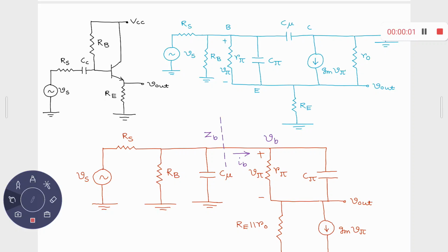Okay, so last day we have been talking about the frequency response characteristics of BJT based amplifiers, and we have discussed one such effect, which is known as the Miller effect, right? In that case, we discussed the frequency response characteristics of a common emitter amplifier, and then the common base amplifier, and then the common emitter common base cascade, which is also known as a cascode amplifier.